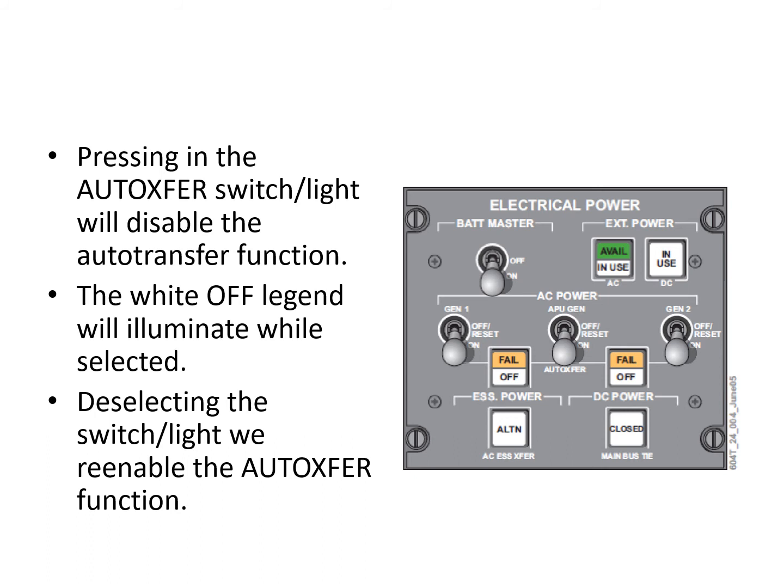So if it should auto transfer but fails to do so, like in the example where we had an overload condition and it's been inhibited, then the fail light will come on. And then you can push the button and switch the whole auto transfer system off.